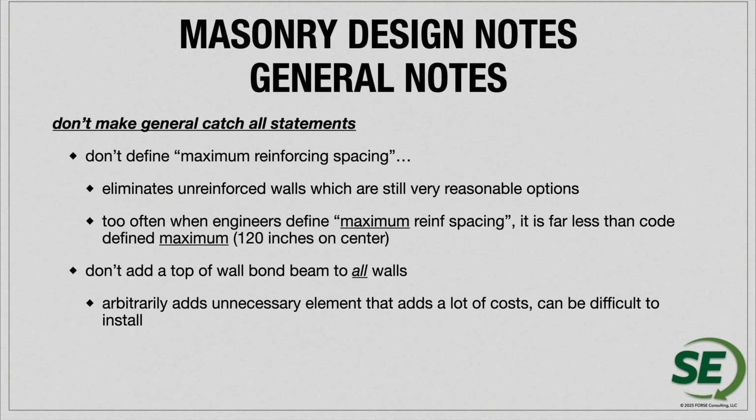Again, before we made points about not specifying catch-all statements, not defining reinforcing, not defining maximum reinforcing spacing. Really, if you do that, then you eliminate the possibility to have unreinforced walls, which are a reasonable option in different areas of the country. And so we really want to have very specific tables to define the reinforcing for a project.